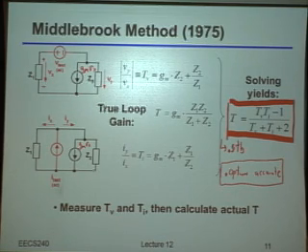The big hammer is start everything at 0 and slowly ramp it up. Because usually, unless things are really bad, which occasionally they are, if things are reasonable in terms of the internal models, everything should be stable at 0 because pretty much nothing is happening. And then as you start ramping up, it'll slowly go from the reasonable DC bias point up to something that should hopefully correspond with reality. Now, even there, you have to be careful because it may unfortunately converge to something else, right? Or it may actually barf in the middle of you ramping the supply like that. But that's typically the biggest hammer for getting around some of those convergence issues.